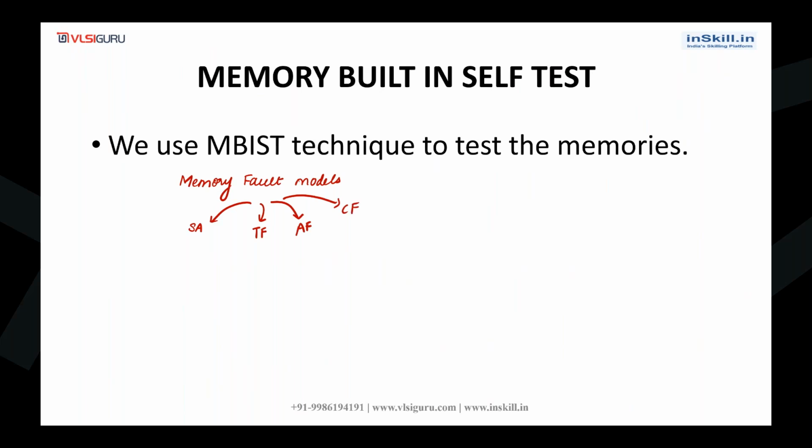During the MBIST part of the training, first we'll try to understand the various memory fault models like stuck-at fault model, transition fault model, address decoder fault model, coupling fault model, all those things.